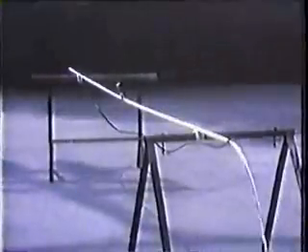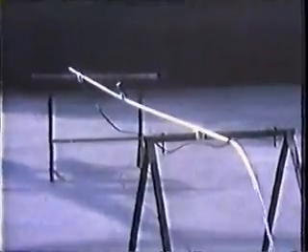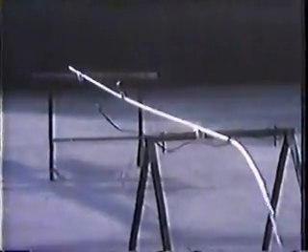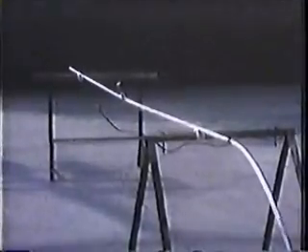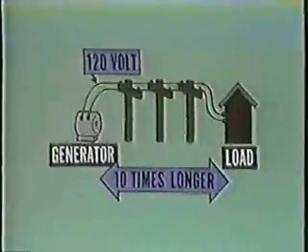In actual practice, what will happen is that the output voltage will be less as well as the amperage, which further aggravates the problem. This loss of voltage is called voltage drop. The analogy of pressure and flow in a pipe further illustrates this relation. If a pipe is made 10 times longer, there will be more resistance, less flow, and less pressure at the output end. Okay, so what's to do?